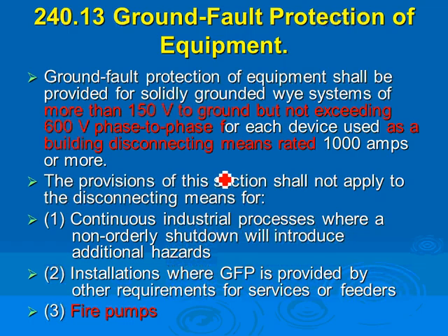So they have a few relaxations for the equipment. We talked about the ground fault protection for equipment, guys. We said the rules for the ground fault protection shall be provided for solidly grounded systems. Do you guys remember the words solidly grounded? We just talked about solidly grounded. If you have impedance grounded, do you need it? No. You have ground detectors on that, not ground fault protection.